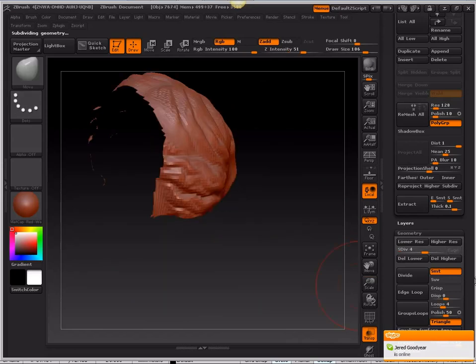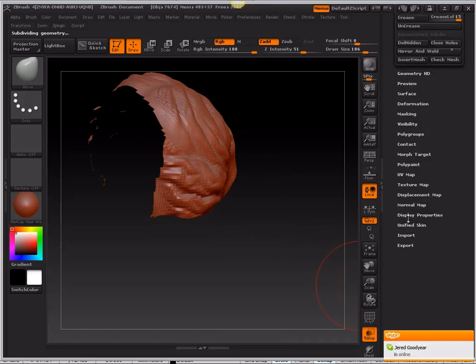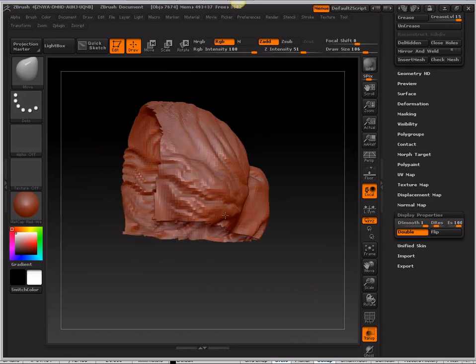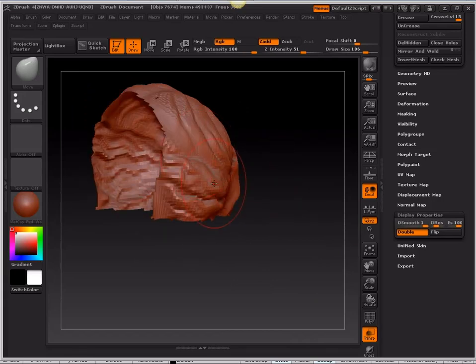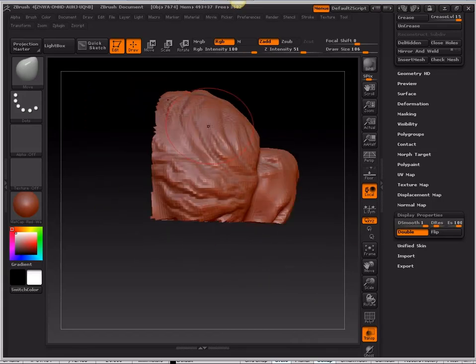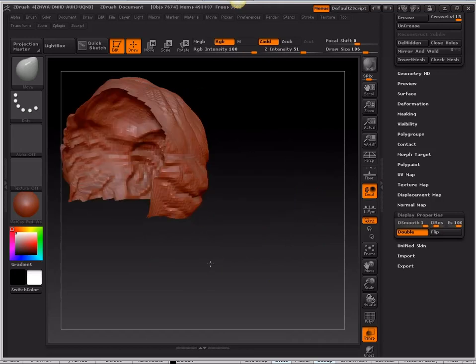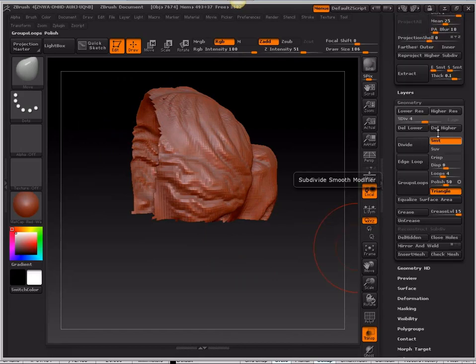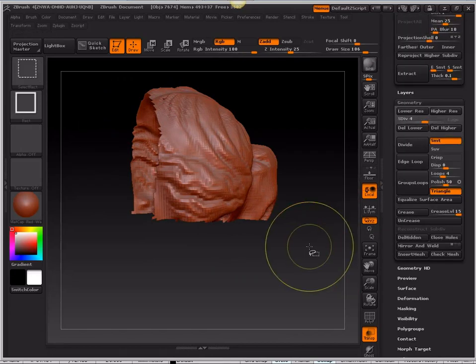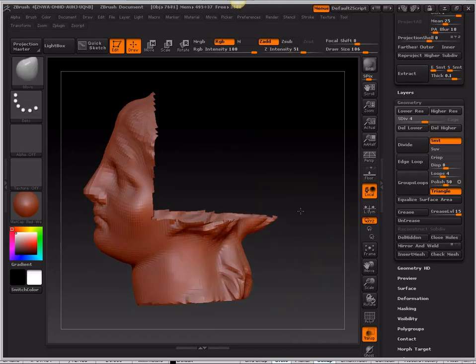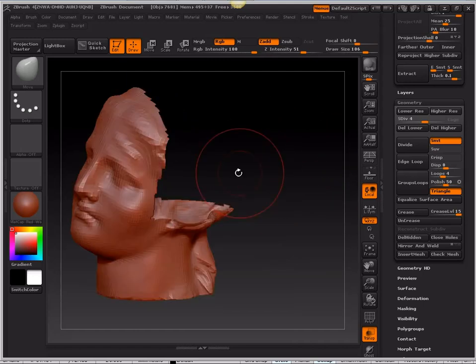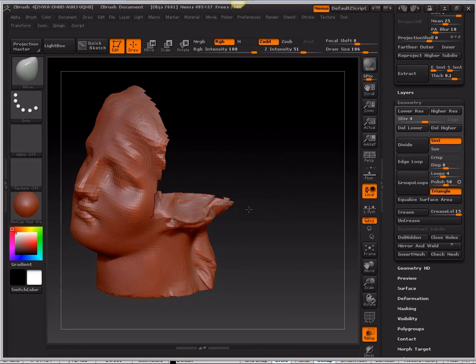okay, if I export now, let me show you in display double faces so you can see what we've got here. If I export as an OBJ now, it will only export the quads that are showing. It won't export the quads that are hidden. So if I export this at level 4, and then I switch, this is a toggle, it's a Shift-Control drag toggle, and this will show me the inverse of that selection.